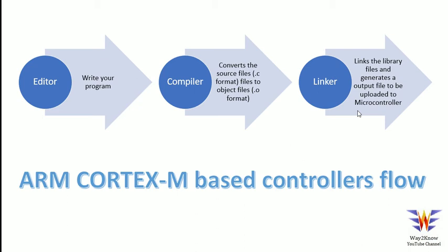This linker links some of the library files of this particular microcontroller, defined by the manufacturer, and combines them with these source files to generate an output file, which will be dumped onto your microcontroller, and then correspondingly the functionality would run. So this is the three-step process: write your program, compile, and then link. Most of the guys use build, which involves compilation and linking in the background, and we just get an output file.